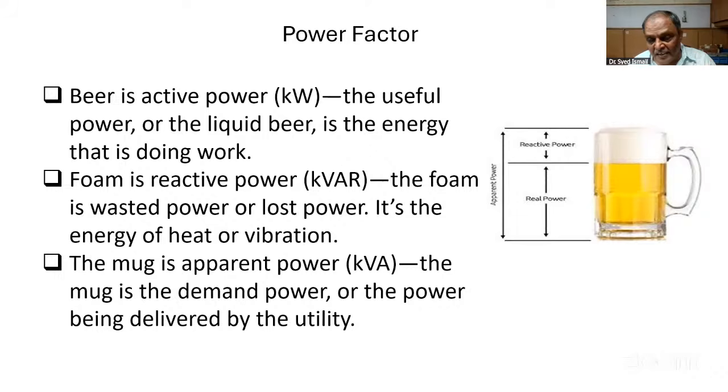So we have to see that every motor has a capacitor bank. That much agriculture people will see to it. We can save 15% of energy in India, in every farm. You guarantee there is a capacitor bank. It's very cheap. Capacitors are in the motors they are using. That's all we require to do. IIT Bombay has done the work, and the World Bank. They have put this capacitor bank on the farm power pole also. So this also will help you. This is a very important problem. We have to correct the power factor. This is called power factor.